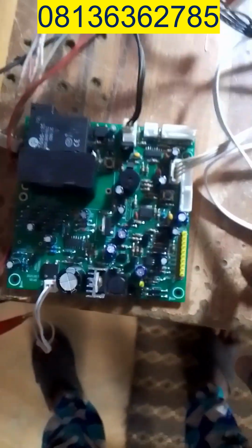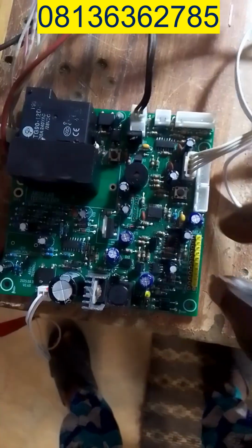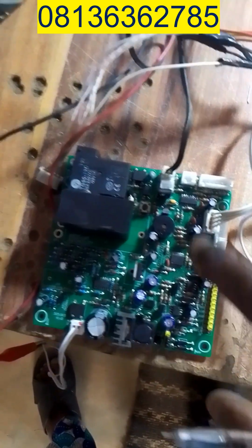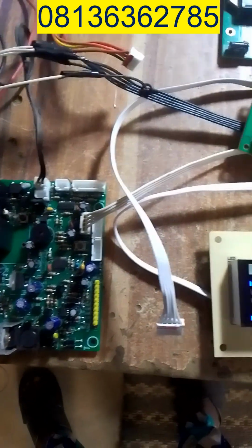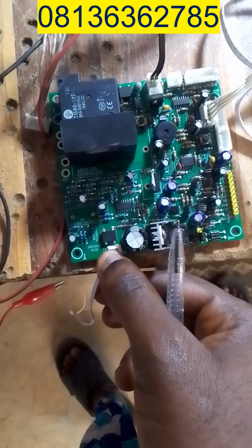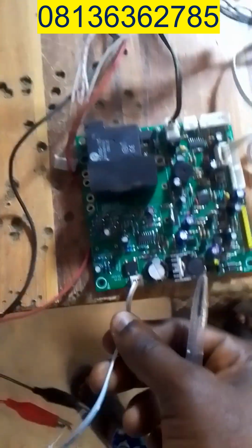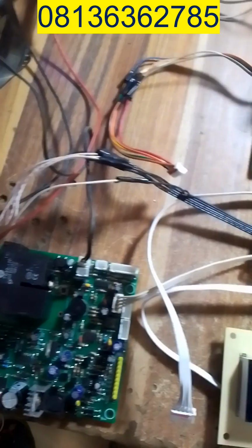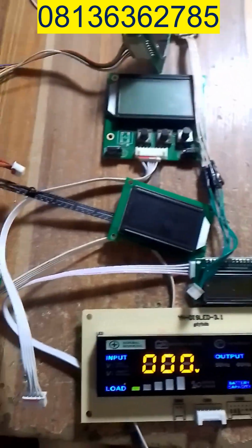Before that, to power the board directly when you want to use it as an inverter, you power the board through this pin. This is where the power supply comes through to the board. But when you want to select the display, you have to put it in diagnostic mode by powering it through this pin here. You supply like 12 volts or 24 volts to this terminal, so the board will enter diagnostic mode. That's where you can select the LCD and change the voltage of the battery system, maybe 12 volt, 24, 36, or 48 volt.